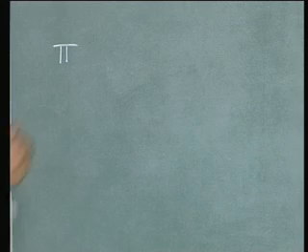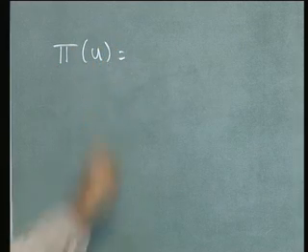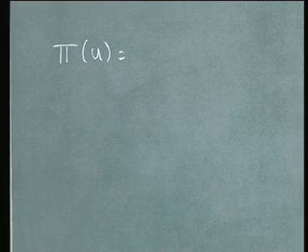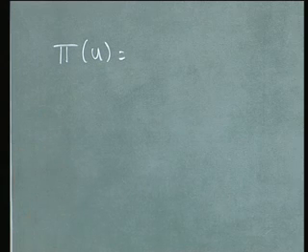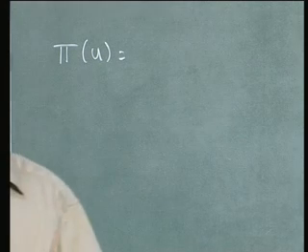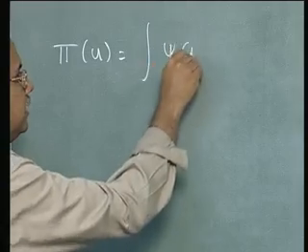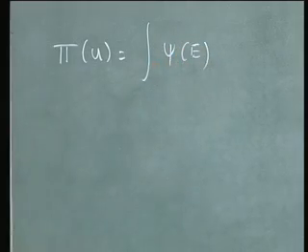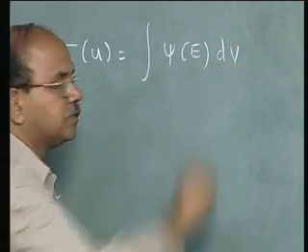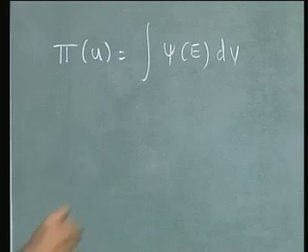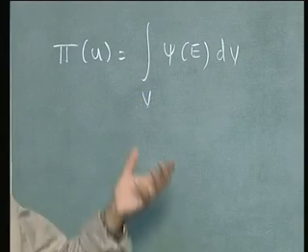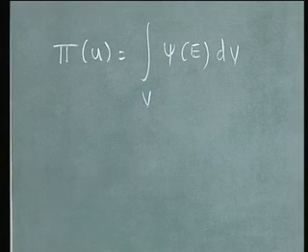This potential, which say for example you can write as phi u, consists of 2 terms. The first term is the strain energy term, and the strain energy term is written, in the large deformation case, in terms of E. So when I write that in terms of E, obviously I have capital V to it, and that's the first term in the expression. You know it from your earlier studies.